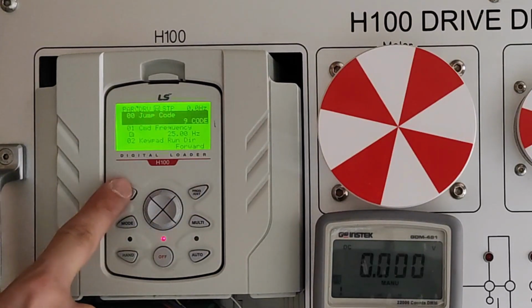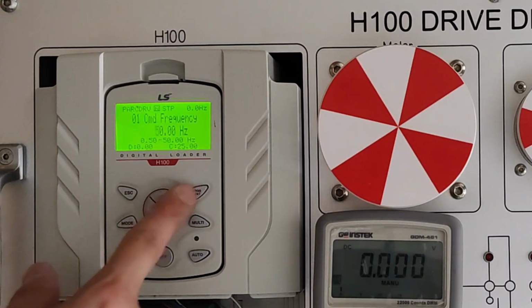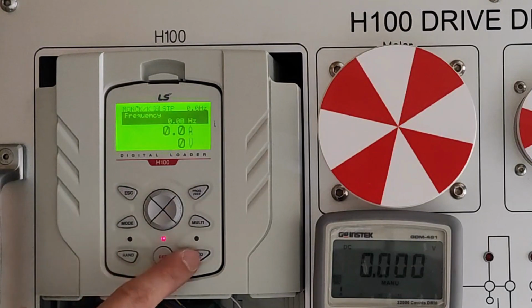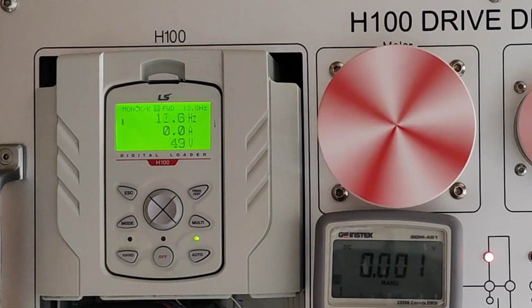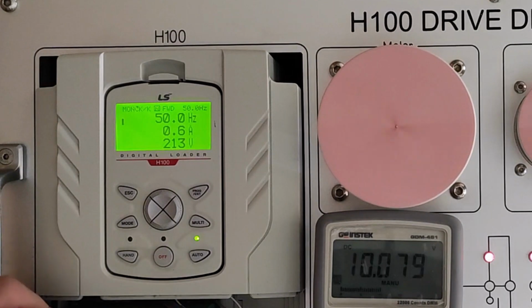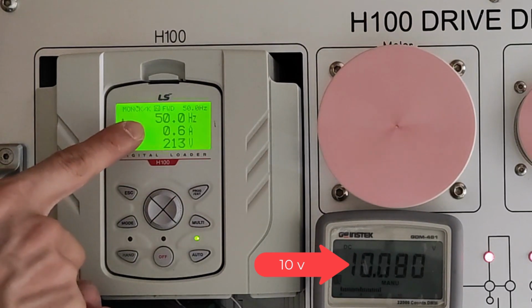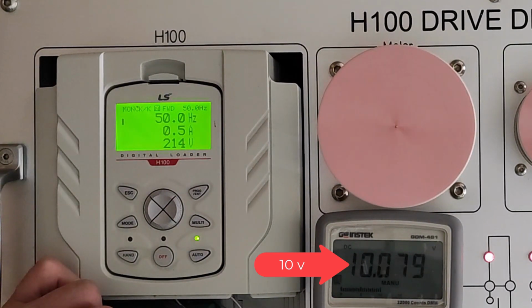So now I'm giving a 50 Hz frequency to the inverter. At 50 Hz, it should give me 10V at the output. Okay, I'm starting the inverter now. The voltmeter is showing 3V. I'm connecting the AO1 and CM terminals. As you can see, my multimeter is now showing 10 volts because I told this inverter to give me 10 volts at a frequency of 50 Hz.